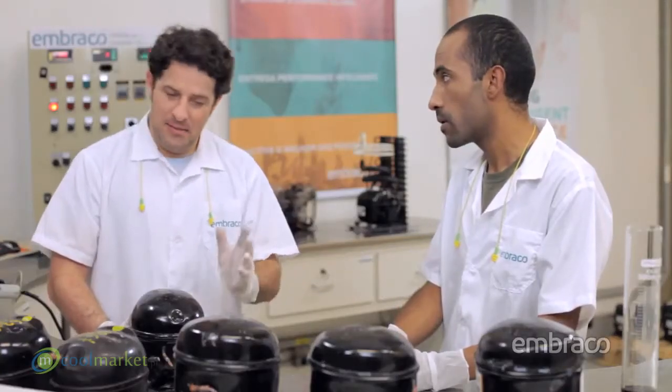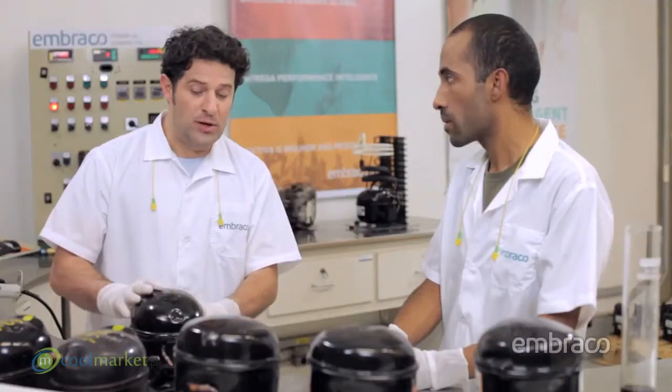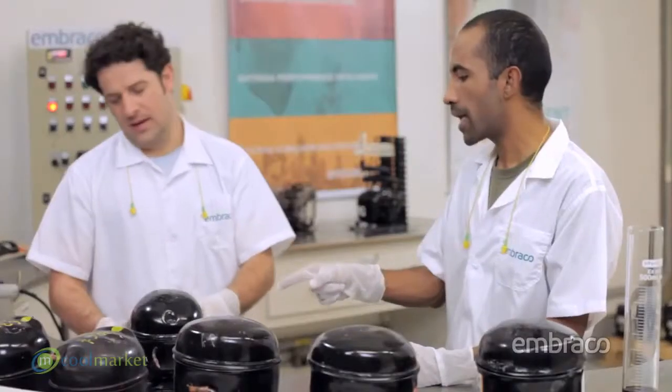Yeah, I've seen some technicians using another compressor to do the vacuum process. Unfortunately, that's quite common, Mark, but a compressor isn't able to reach the recommended vacuum level, which is 500 microns of Hg. Right, and what's the vacuum time required to remove all moisture from the system? The ideal is to have a vacuum pump with a pressure gauge and ensure that it reaches the recommended vacuum level. Generally, the vacuum time varies from 30 minutes to 1 hour, depending on the size of the system.